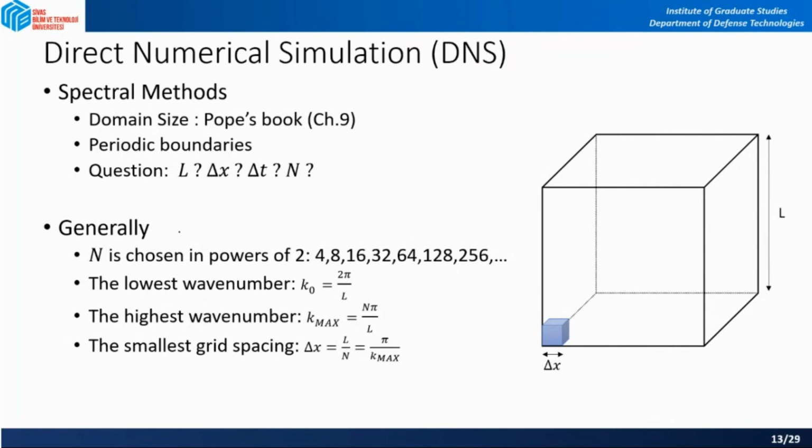LES is very much related to DNS. We will see LES as well. And then all the modeling stuff that we will see later, like the eddy viscosity models, Boussinesq approximation, K epsilon, K omega, are quite standard right now. And for complex engineering flows like combustion, or RANS-based models, Reynolds averaged Navier-Stokes based models, they are really not working.